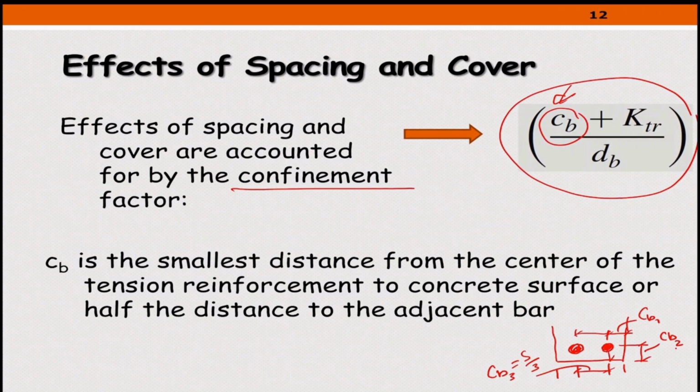Also, remember when we selected the minimum, it was for this reason as well, not only for making sure the concrete we pour would reach the bottom, but also because when having the steel bars very close to each other, concrete in between tends to split, and when concrete between the bars splits, it would reduce the bond between the bars and the concrete.